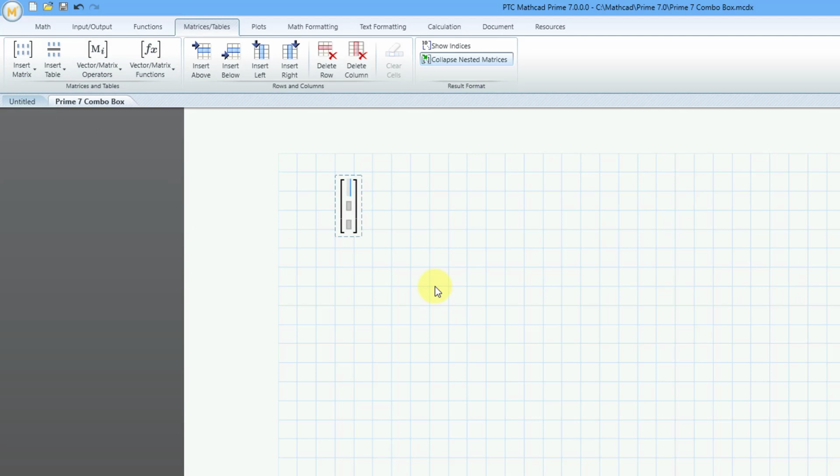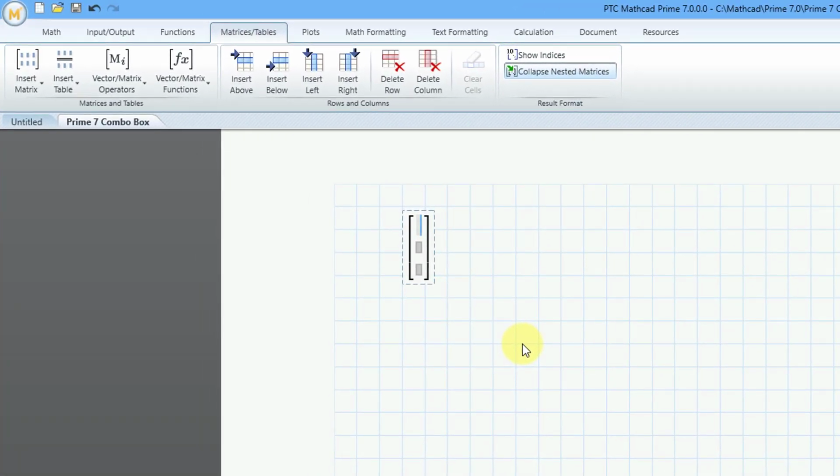And so in this input box, I want to have people be able to assign the value of density and Poisson's ratio and Young's modulus. So let me create the row character, the letter R, and then Control G. And then I'll use the down arrow on my keyboard to go to the next element of the vector. And this will be for Poisson's ratio. I don't think there's a standard symbol for Poisson's ratio, so I'll just write Poisson. And then for Young's modulus, I will use E.